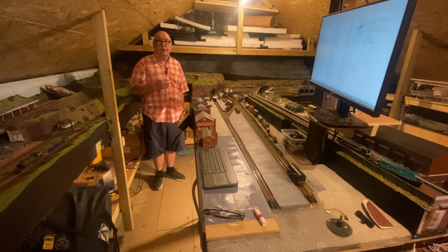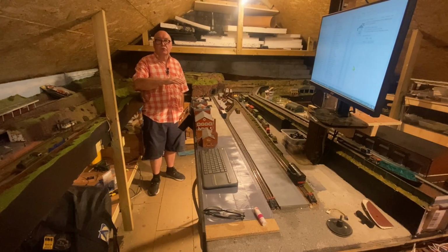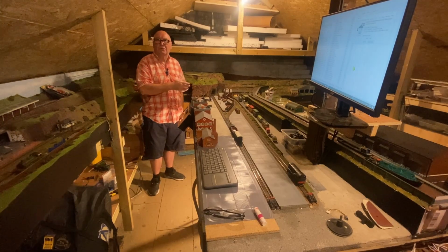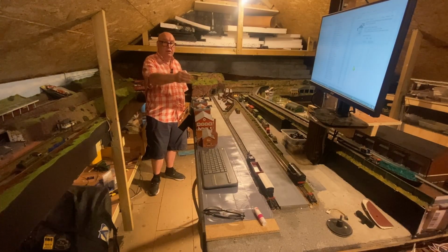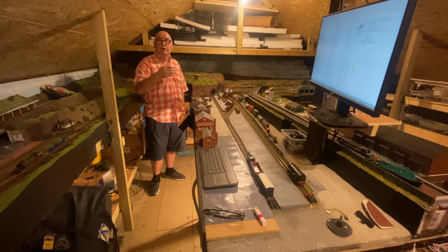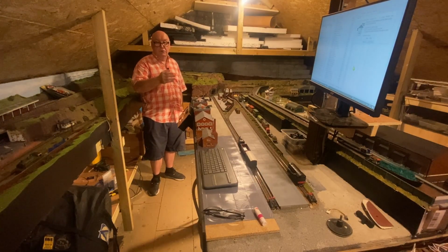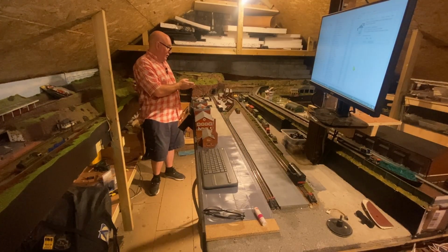And in this case, we're using a 2-wire CAN bus network. Now, this could be done just using JMRI and scripting with timing. So you could time how long the train takes and then do it that way. But I'm actually doing it using 4 spot detectors which are underneath the track. They're feeding the signal back to JMRI. JMRI then tells DCC-EX, or my command station, to change the speed and direction of the loco.